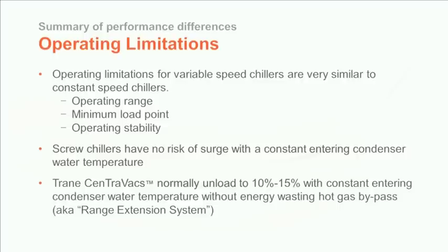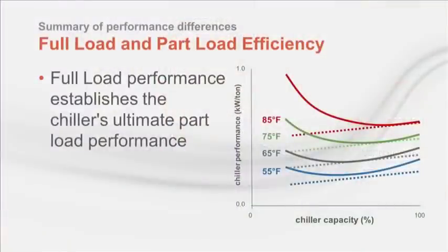by some manufacturers. With all this talk about part load performance, we dare not neglect to mention the importance of full load chiller performance to system efficiency and improving financial ROI. For any given modulation technique, the chiller's full load efficiency anchors its ultimate part load efficiency. Putting a variable speed drive on a chiller is an upfront investment which may have a relatively long financial return on investment depending on the specific application.